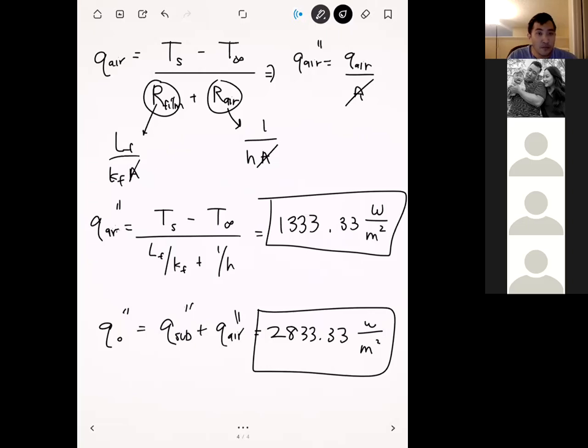So we could apply that for like on an engine or when we look at engines and whatnot. Yeah. So anything that has multiple layers where you have heat that's passing through, thermal circuits work great for these because they handle those things really easily. Because anytime you have a separate layer, you just use a resistance to represent that. Okay, thank you.